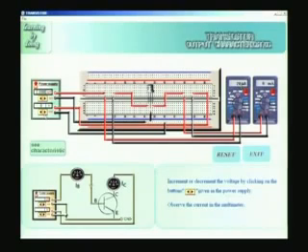Now let me keep increasing the VCC, and as I increase, please observe what happens to the IC. You would find IC keeps on increasing. The moment I come to 2.5, it is now 4 milliamperes. Beyond that, you find it continues to be in 4 milli. It has already reached the saturation value and it is now 4 milliamperes for all the different voltages that I apply at the VCE voltage.